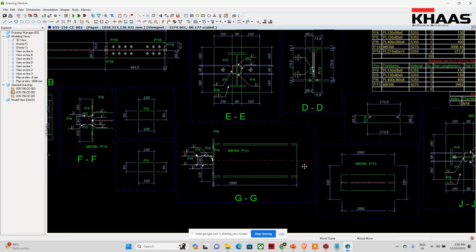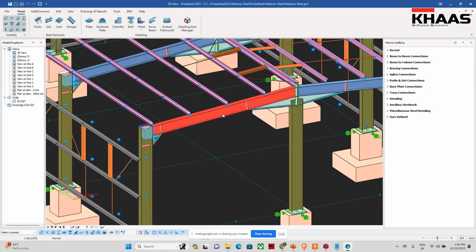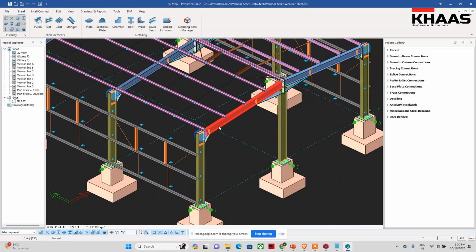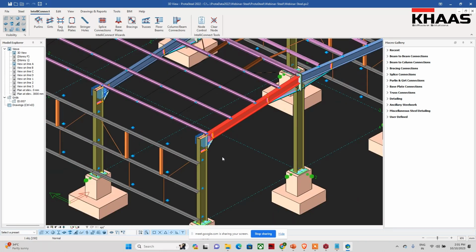Great. Can it be done only from model to drawing, or if any change is made in the drawing and we upload it, will the model be updated? Yes, sir, understood. We have to make the model changes. There are some limitations. Let me show you, Control D for the model. Arrangement, offset, moving from one location to another, copy paste, all these things can be done. If you want to place the column itself, that is not possible here. We have to go back to ProtaStructure and create it anew. All modifications we can do, but geometry creation, modeling creation, and grid updates should all be done in ProtaStructure.